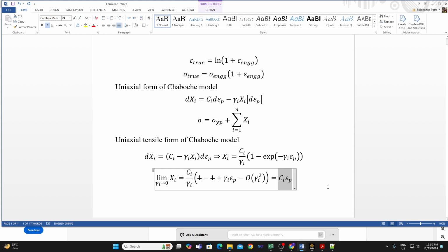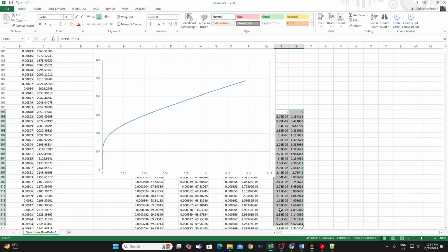So, for example, if you look at this particular plot of the stress versus plastic strain, after some initial settlement, this curve is more or less linear. Okay, and we have actually done the calculation, and we figured out this particular slope is around 2 GPa or 2000 megapascal. Okay, so this portion is linear, so there is some initial settling that is happening.